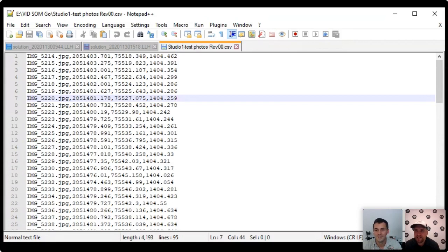Okay. So Rice is asking, without 3D survey and photos, only the points, how the measured GPS points are exported. We export via CSV or text file. Both formats you can use in any CAD-related program, so they're the most widely known, and we stick to those two basic export functions: CSV and text format.